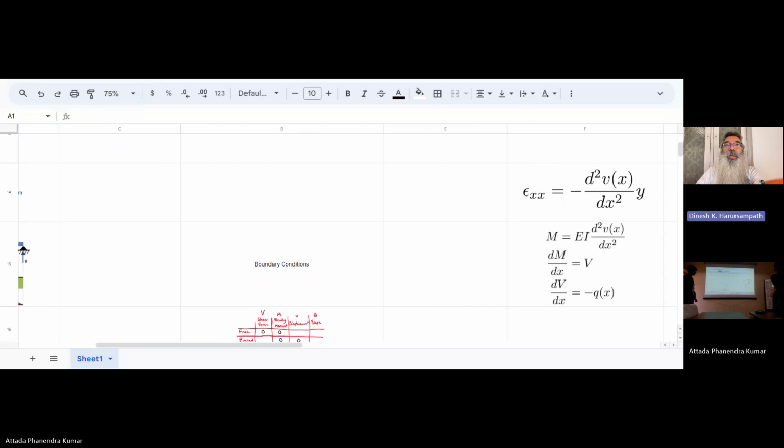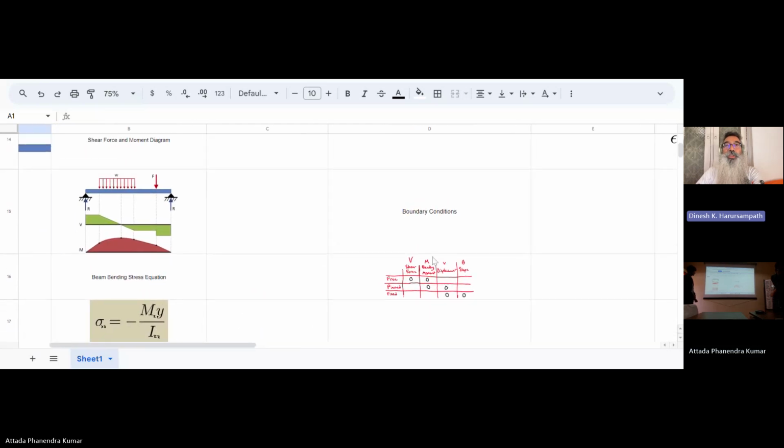So once again, if you look at D15, you're talking of boundary conditions, right? So you put it under constitutive law. But boundary conditions are not under D, which is constitutive law. So you can't put boundary conditions under constitutive law. There are two types of boundary condition. Either you put, let's say, a fixed support or a hinge, and then you're essentially defining, for example, that the displacement has to be 0. So that's essentially a boundary condition in terms of the geometry.